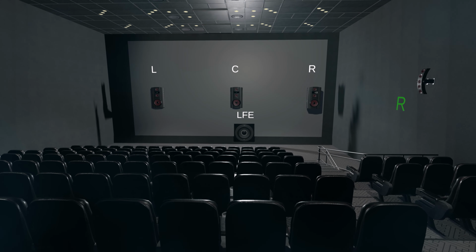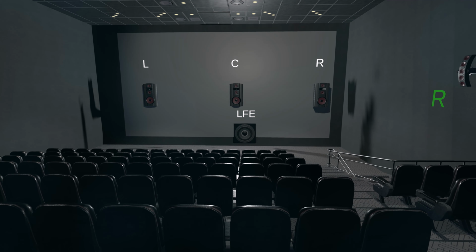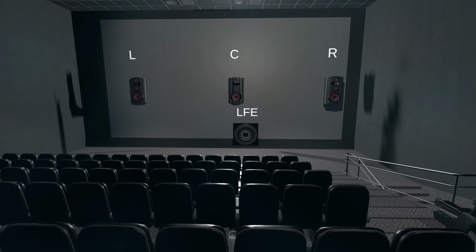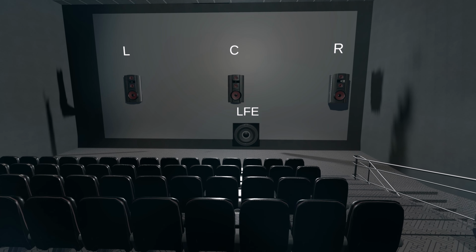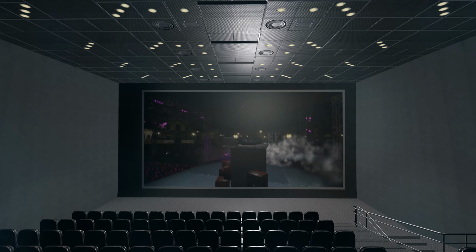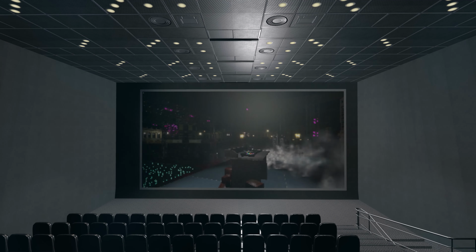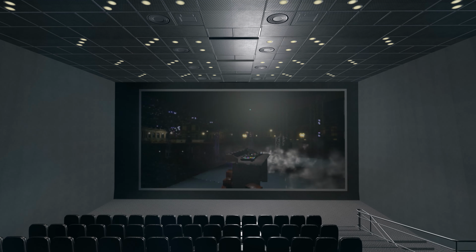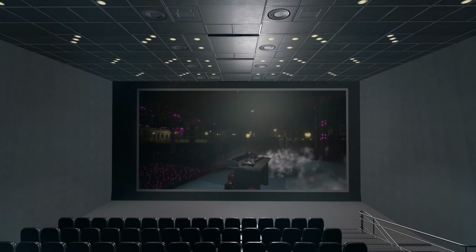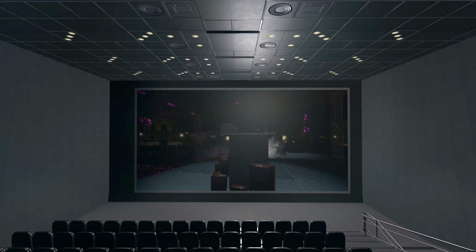LFE, low-frequency effects. A separate low-frequency channel was introduced to reproduce special low-frequency content. This LFE channel normally has a bandwidth of 20 Hz up to 120 Hz and is set 10 dB higher than the surround channels. It should not be used for the entire low-frequency content of the multi-channel sound presentation. The left and right channels are equipped with their own independent subwoofer systems. The LFE channel should only carry the additional low-frequency enhancement information or effects, such as explosions.